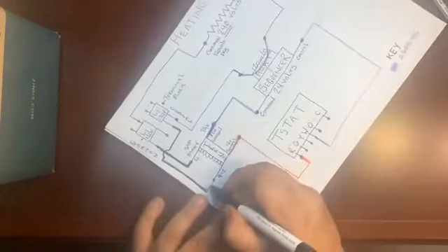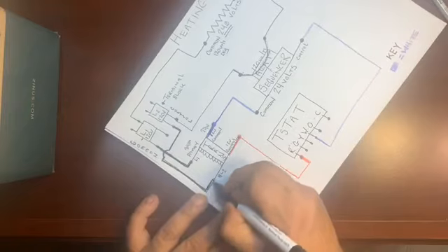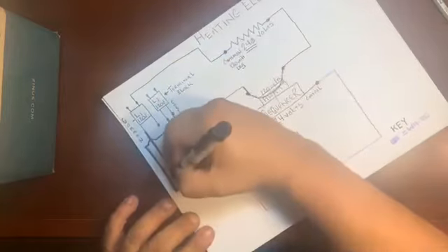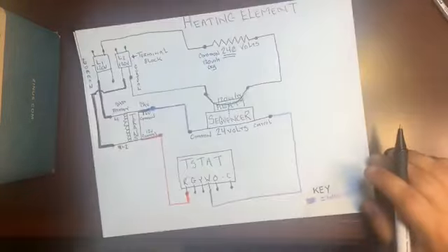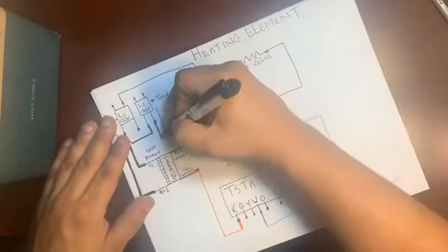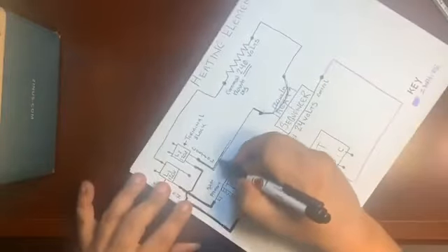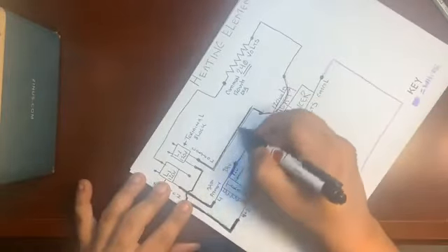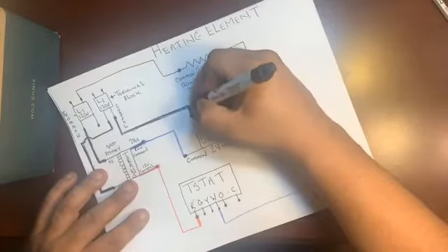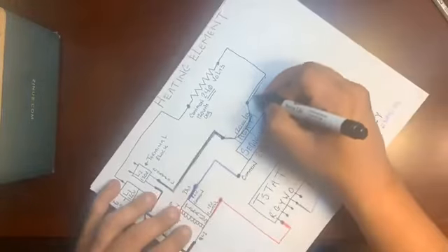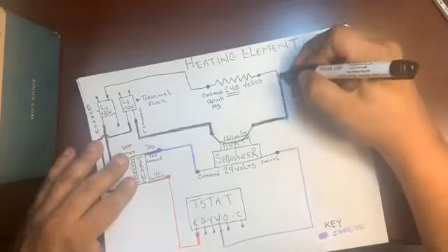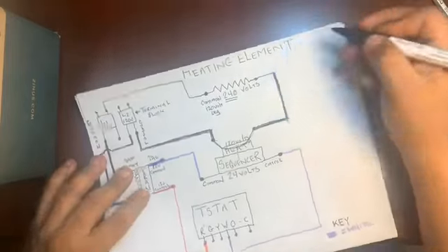So your diagram is going to have to show this as well, that your high voltage wires, which is anything that comes off L1 and L2, are thicker on the diagram. See how much thicker these are now? And this has to go all the way through here, because this is a high voltage wire. Much thicker than the low voltage wire in the diagram. And the key will reflect this. We will write this in the key so anyone looking can see the thickness in wires and understand what is high voltage and what is low voltage just by looking at it.